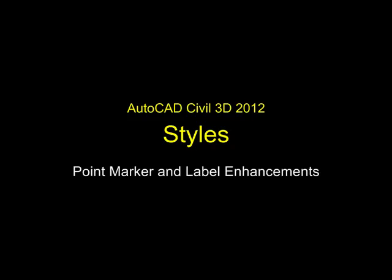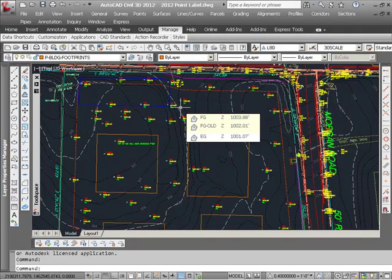Well, a couple of new and useful options for controlling your points and point markers have been included in Civil 3D 2012. You can now rotate the point label and the marker separately for greater control over the placement of the point object. Also included is a new text wrap for your descriptions.